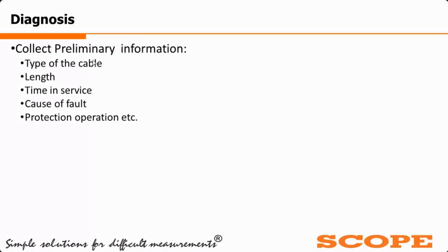After that, we have to note down the cable time in service. After that, we can also note down the exact cause of the fault. And also, if any protection operations have happened, according to that we can determine the exact cause of the fault.